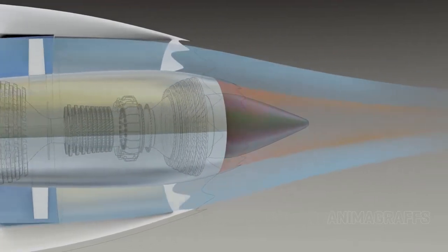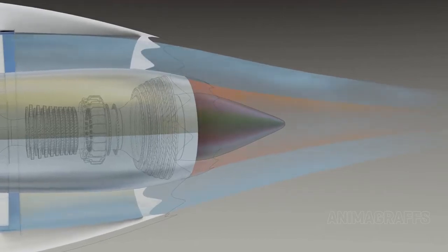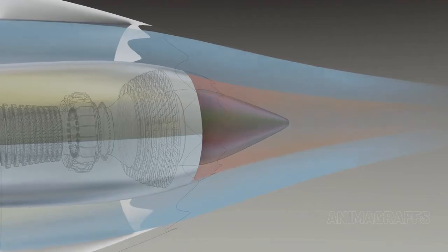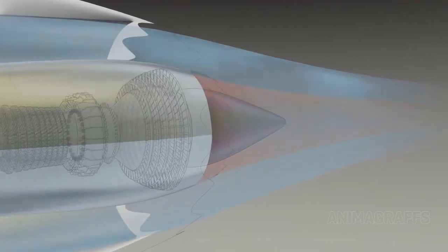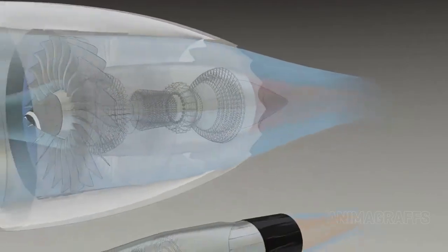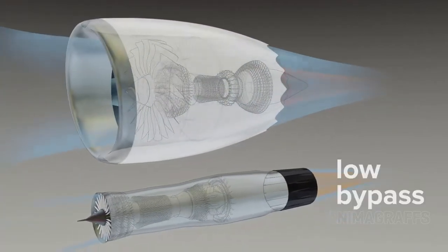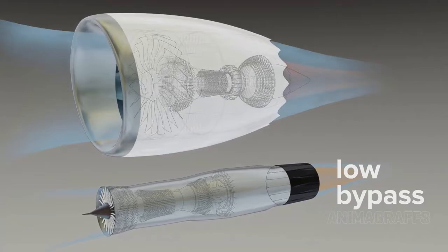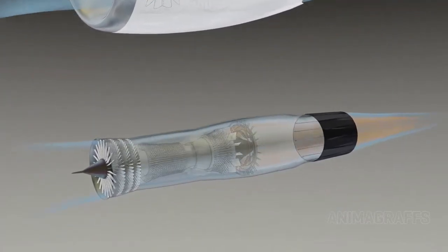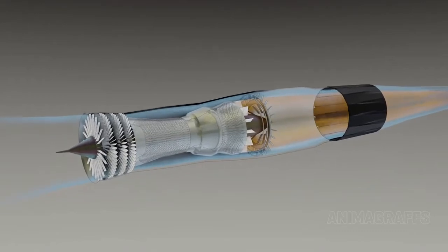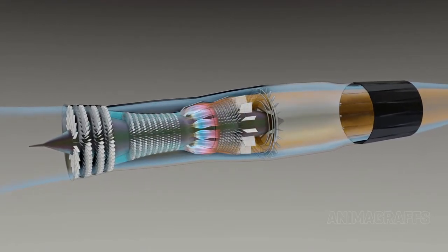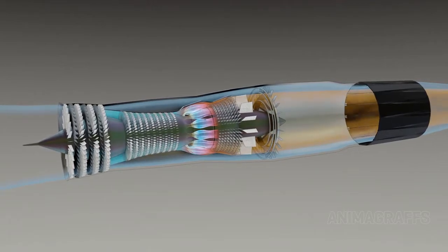Exhaust velocity is a major factor in jet engine noise. High bypass engines surround fast-moving core exhaust with large quantities of slower-moving bypass air for quieter operation. Military fighter aircraft use low bypass engines which are more compact, have high power to weight ratios, plus supersonic and afterburner capabilities, in exchange for things like poor noise control and high fuel consumption.